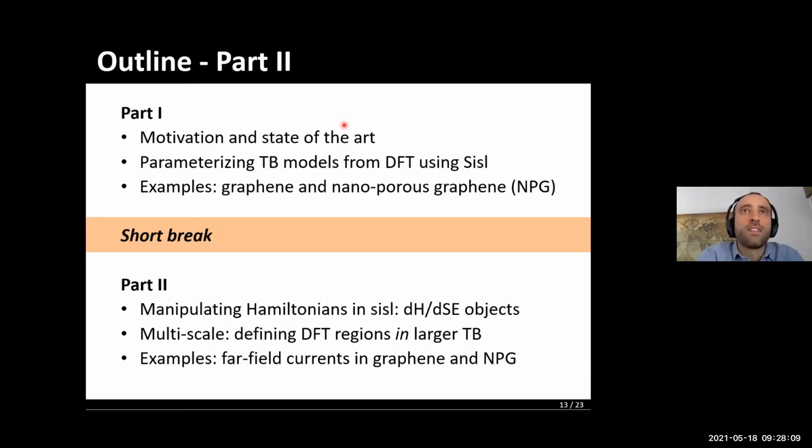Then Guido is asking, in modeling two top contacts in SIESTA, since the initial calculations adopt periodic boundaries, is one practically putting a finite, non-periodic device with cut contacts separated by a suitable vacuum region before applying the electrode self-energy? So I'm not really sure about what you're referring to, maybe to the simulation that I've shown in the introduction that had two top contacts.